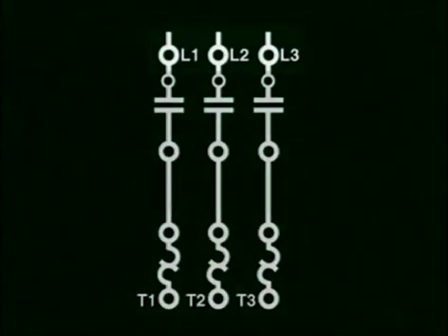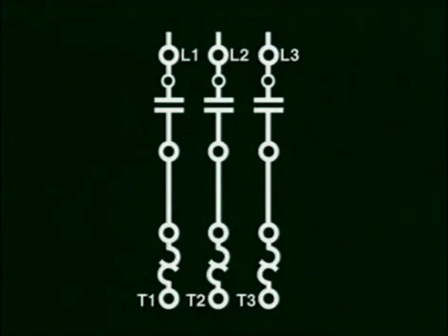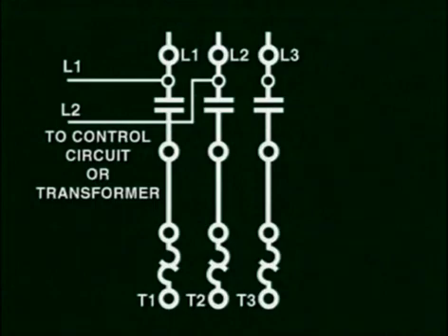From the top, you have the three terminals that connect to L1, L2, and L3. Immediately below the power terminals, you will find another three terminals shown in smaller circles. These terminals represent and are used for the wiring connections of control circuits, which will be represented in thinner lines as opposed to heavy lines for the power circuits. We'll see these connections in a second.